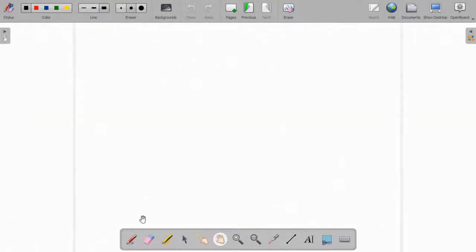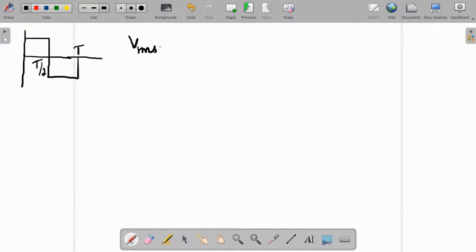இதே, நான் சொன்ன மாதிரி if you have a square wave, ஒரு pulse input ஆயிருக்கு அப்படின்னா, what is the general formula to find V average and VRMS பார்த்துட்டு then special cases பார்க்கலாம். So time t, so this is t by 2, a symmetrical wave. So formula to find VRMS, rms voltage is given by root of 1 by t integral over t v square dt.